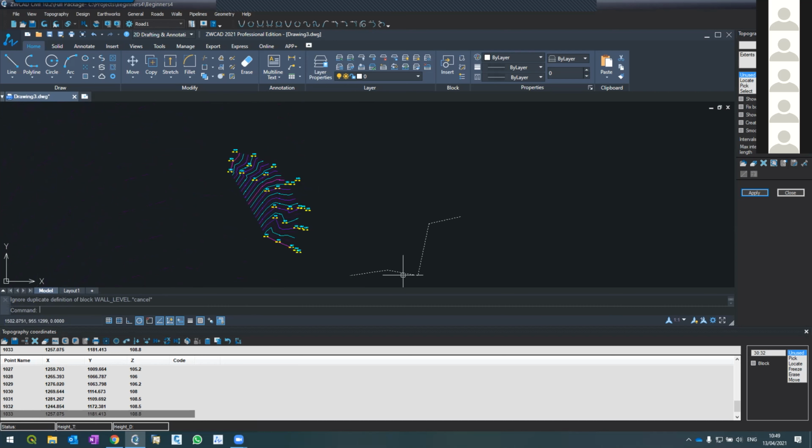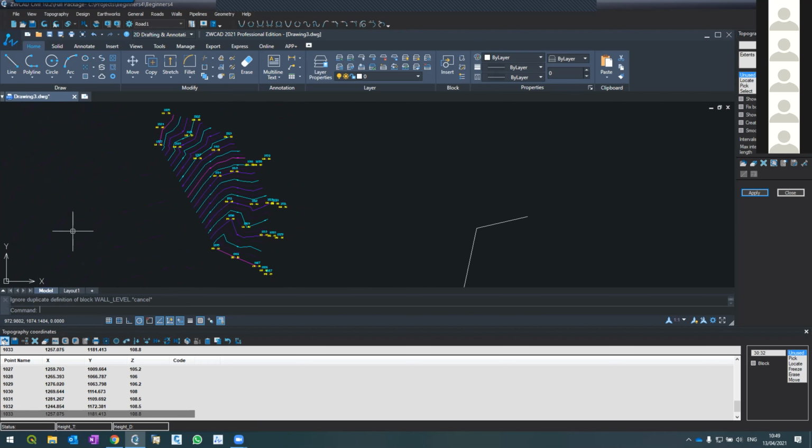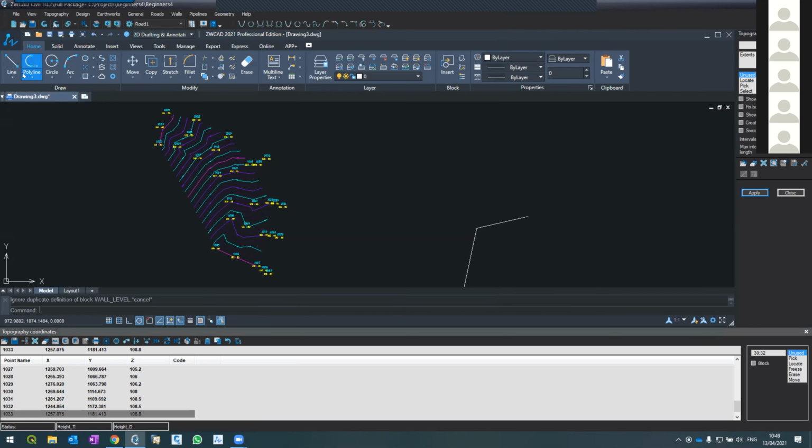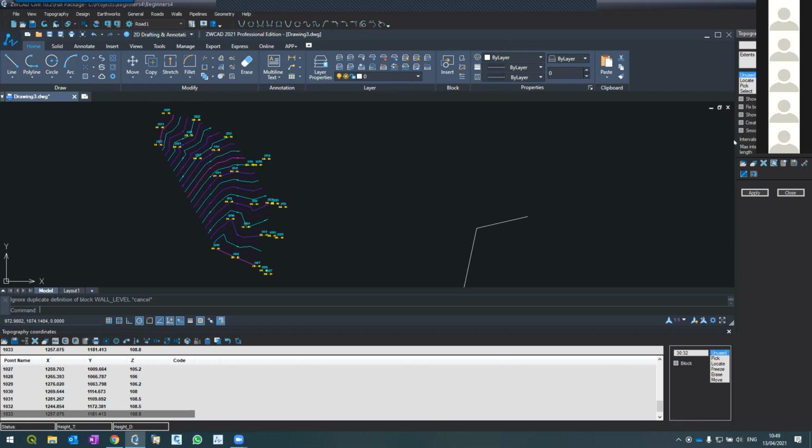I finished with my road. Then I climbed up, and this is only 5 meters, not that high. And I surveyed 2 points here and continued 2 points here, 2 points here, and 2 points here. And I came from the field. I loaded, like open it from here, like we did for sample 7. Load the coordinates, press refresh. So the coordinates, I'm okay. I'm going to topography contours like you did, and enter 0.25 and press apply. Let's see what will happen.